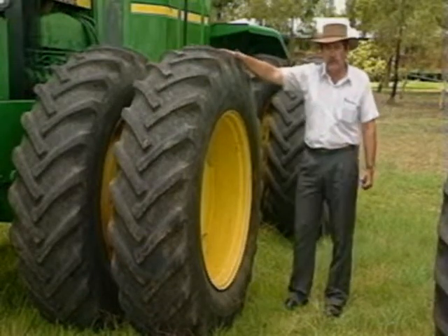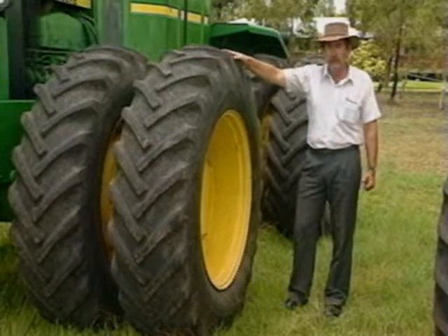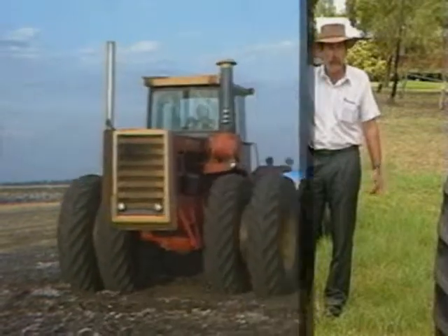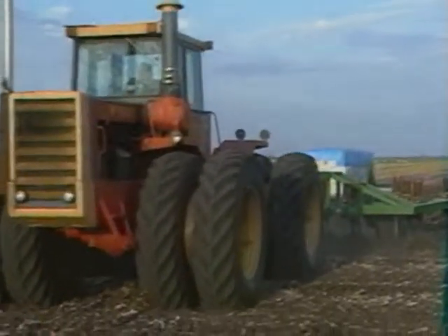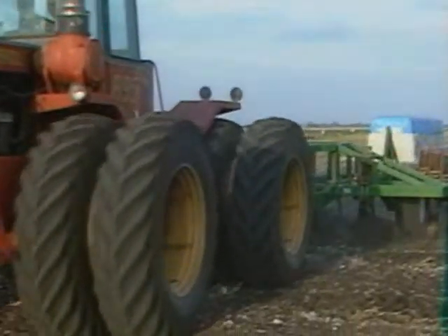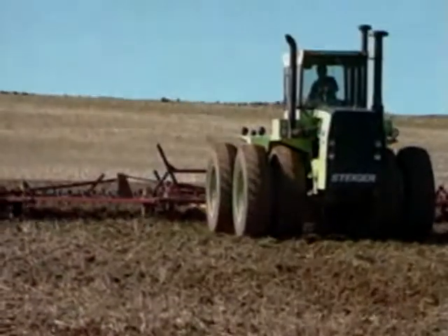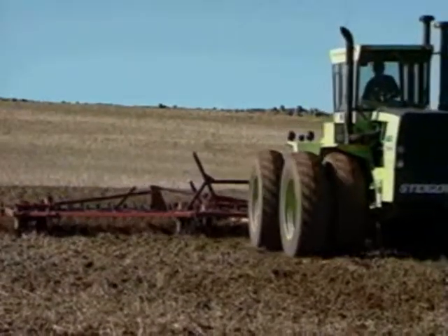Of course, this is not the only contributing factor to tyre life. Soil conditions, we find in the Darling Downs area, in the heavy clay soils, we can get hours as low as 1,500, and then if we go across to sandy soils of, say, Western Australia, we find that we can get up to 6,000 to 7,000 hours out of a set of tyres.